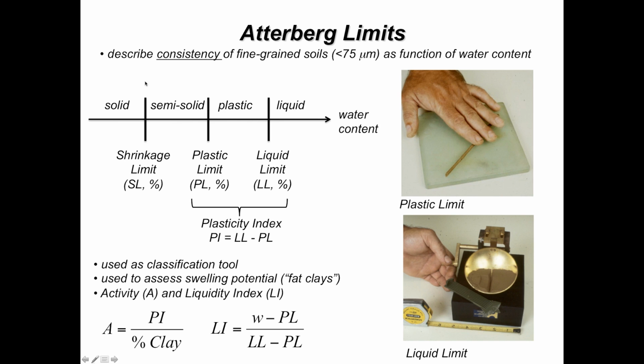The plastic limit, which we measure using this thread rolling approach generally, again defines the water content between the semi-solid and plastic state. And so again, there's that difference, the plasticity index.